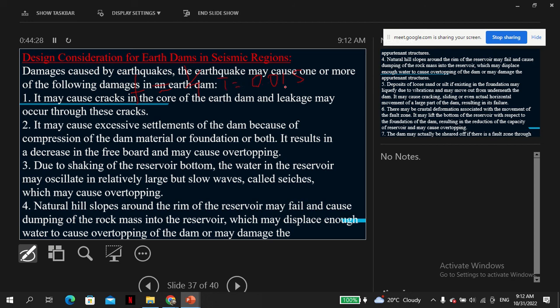Now this, if you check, coincides with the natural frequency of buildings of 10 to 12 stories. So in the experience of those countries, when an earthquake occurred, every time these buildings in this range had severe damage, and people wondered why.